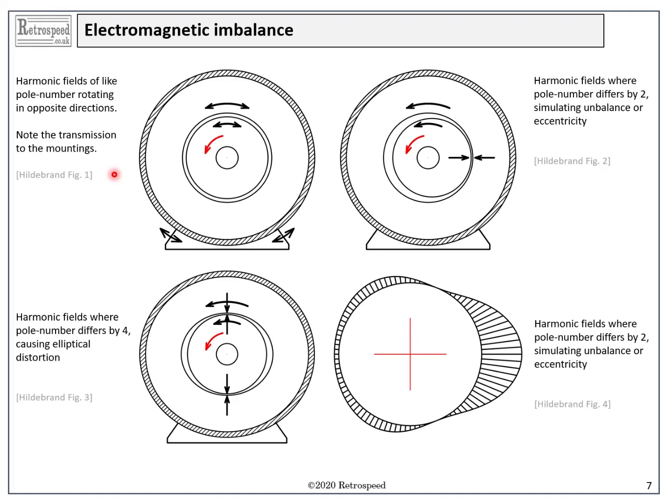The problem with this oscillatory torque is that it is transmitted directly to the mountings, which provide a path for the transmission of noise. For this reason, single-phase motors are often provided with compliant or resilient bearing mountings, springs, to attenuate the transmitted torque oscillation.